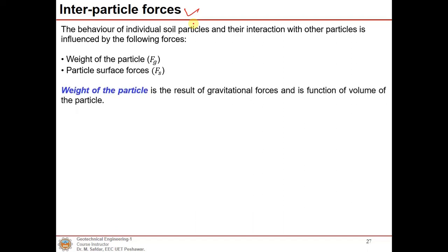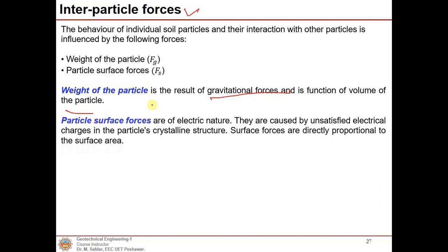Weight of the particle is the result of gravitational forces and it's a function of the volume of the particle or density of the particle. Particle surface forces are of electric nature. They are caused by the unsatisfied electrical charges in the particle's crystalline structure. Surface forces are directly proportional to the surface area.